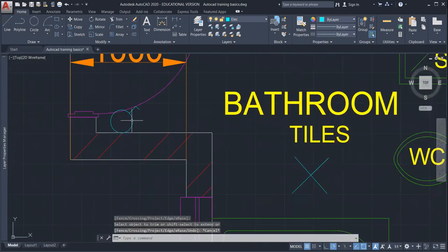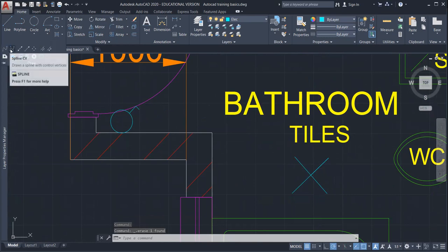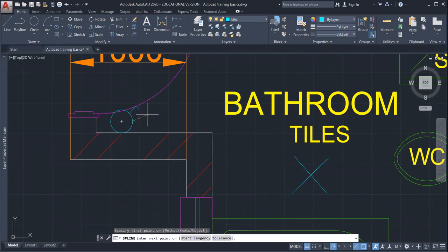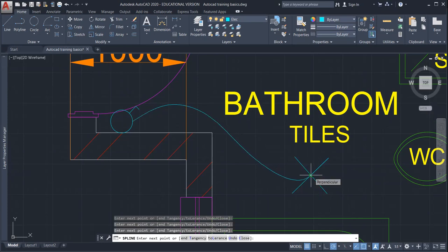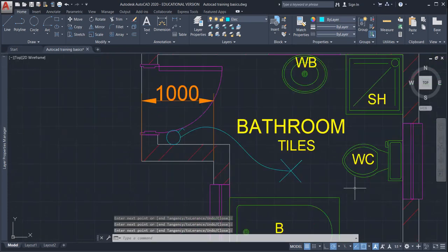There we go. And now to connect them together, there's a polyline. Then you just do this. Oh no, it's not this one I'm looking for. We want it curved, so delete. And then at draw, look, there we go. This is the one I'm looking for. Also this one, fit points. Let's try this. It's spline that you're looking for. Yes, there we go. Spline. And then if you're there, you just press enter, boom, that's good enough.